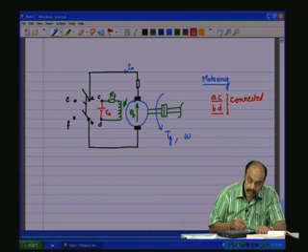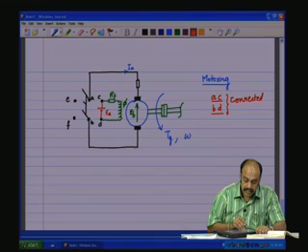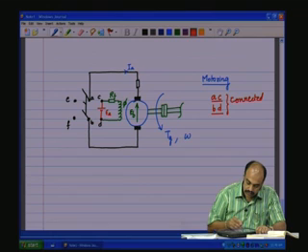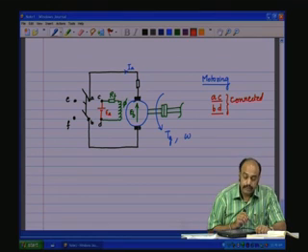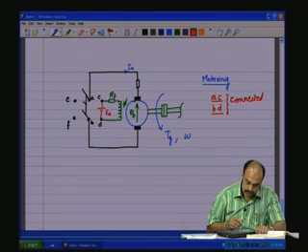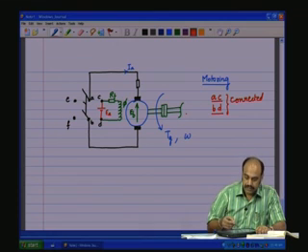That is, here we put these double pole, double throw switch to positions C and D. So, which means the armature voltage is applied to the brushes of the motor. So, this will cause IA to flow and therefore, motoring will happen and then there will be generated torque and therefore, the speed.